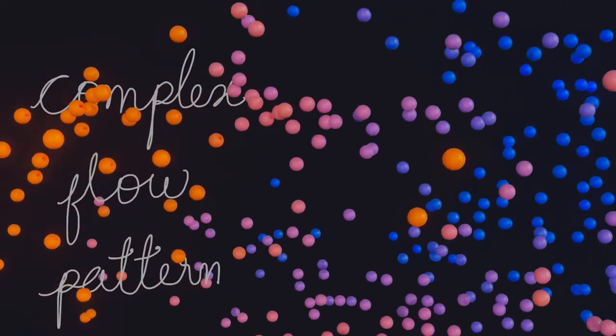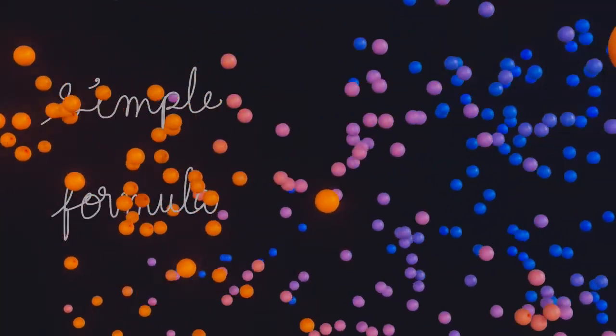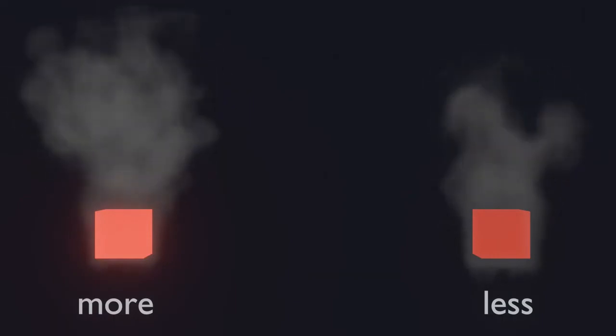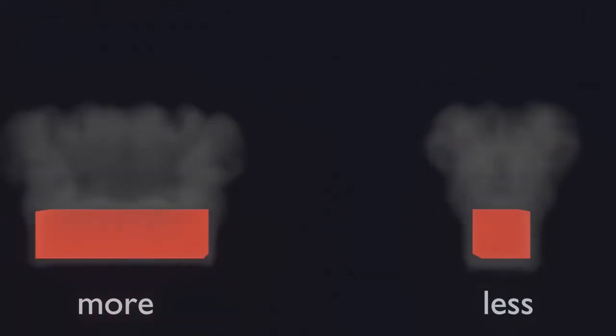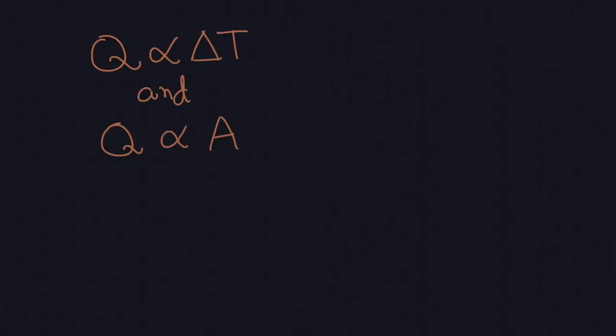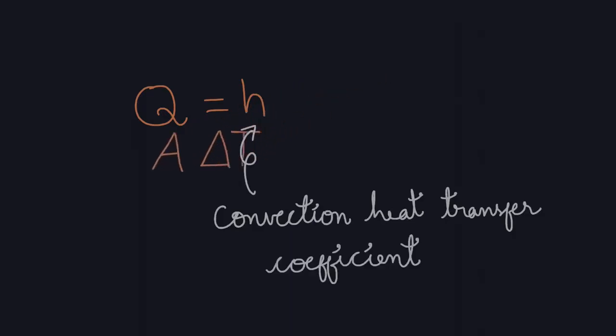Despite its complexity, convection heat transfer can be estimated using a simple formula called Newton's law of cooling. According to this law, the rate of heat transfer is proportional to the temperature difference, and it is also proportional to the surface area from which heat transfer is occurring. So to avail some mathematical benefit, the proportionality has to be removed and a proportionality constant needs to be placed. This constant is called convection heat transfer coefficient.